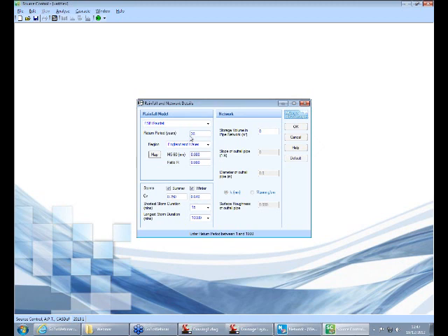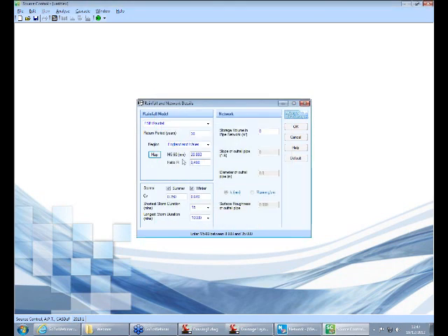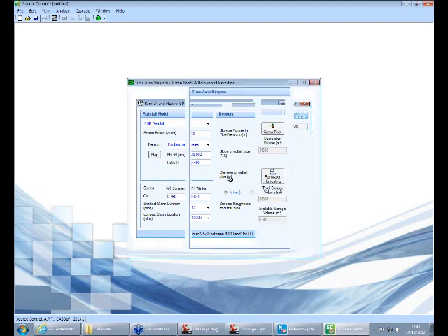So we're designing it for a 30-year return period. We just click on the map and grab Swindon for our rainfall of M5-60 and ratio of 20 and 0.4. We'll be running all the storms from a 15-minute to a 7-day storm, but we won't include any of the network details upstream because we're taking the water basically directly off the roof and into our storage structure. We go OK on that.